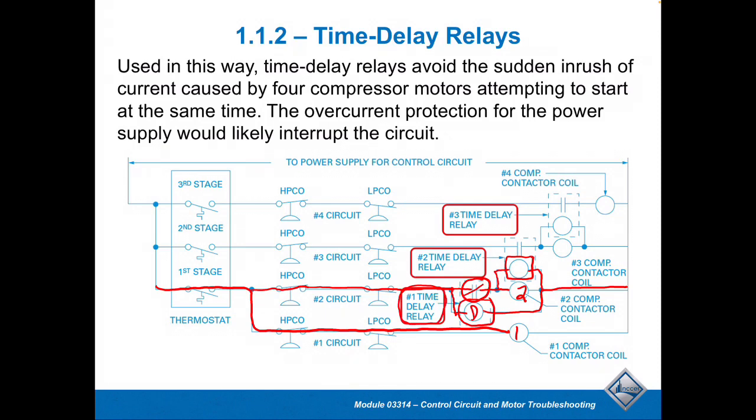So those are delays. They're not like a normal relay where I energize it and expect an action right away. These are ones where there's a delay in there, and that is its purpose. And then of course, further, the need for cooling closes those circuits. We go through the high pressure cutout, low pressure cutout, and then we go through these contacts.